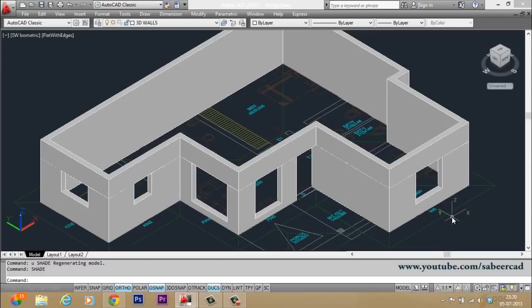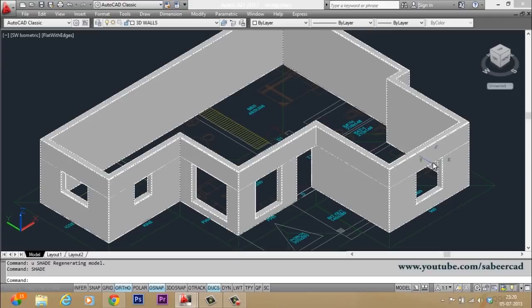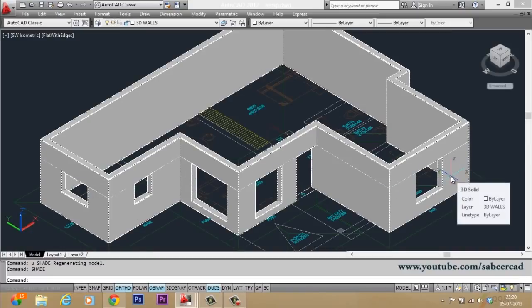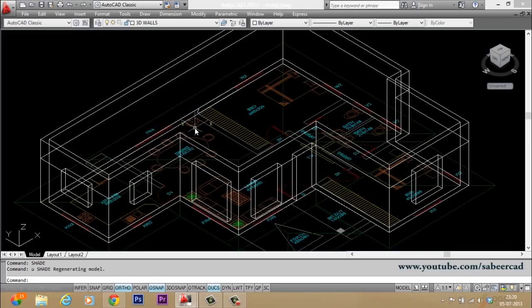This is how it will appear. Now you can see that you have created cutouts for the doors and windows only on these sides because I actually want to create a southwest view. So even if there are doors and windows on the other sides, you don't have to model or create those windows because those objects are not going to be captured by the camera.